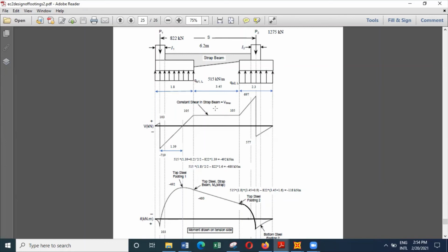the shear carrying capacity of concrete, because generally we know the shear carrying capacity of concrete is around 0.35 and above, 0.35, 0.36 and above. And the shear stress we get is only about 0.31, which means the shear stress is very low, which means we might be able to just provide nominal links. Or the minimum links, we'll be able to provide the minimum links in the beam. And then for the selected minimum reinforcement, the minimum links, we can find the shear resistance.